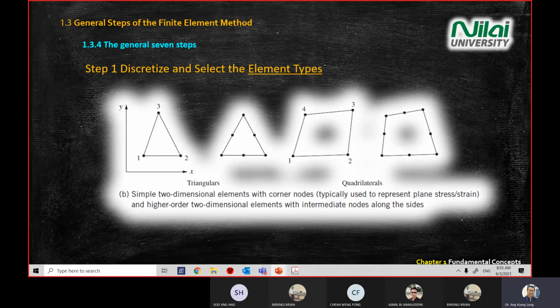Okay. How you can break, or in finite element or in your Ansys software, you can choose different types of element. If you deal with 2D element, then you have all the shape that you can see on the screen here. You have rectangular, you have a 2-point, or you can have a rectangular consists of 6 points. Of course, more points, it will generate more data for you. It can be more accurate, and also it can be generating more error if you key in the wrong input. All right, or quadrilaterals that you have the shape of this one, or more nodes or more points.